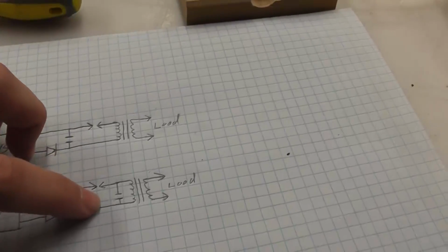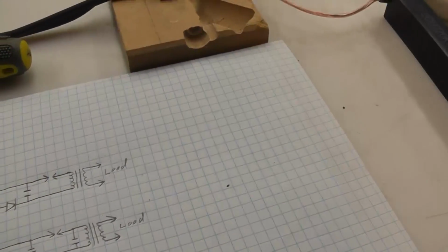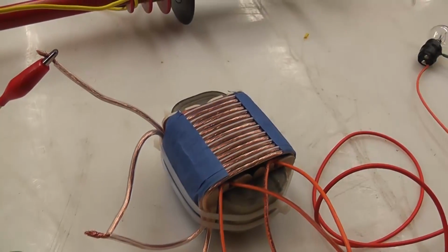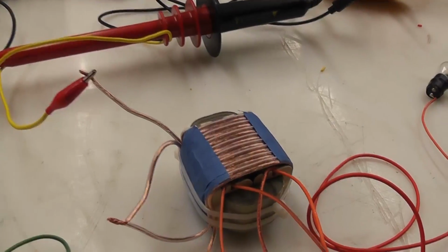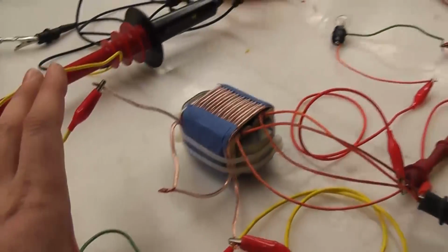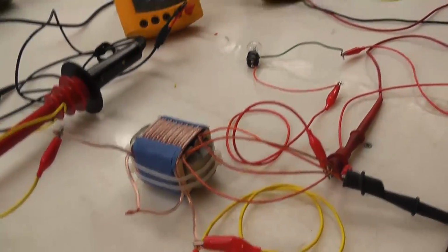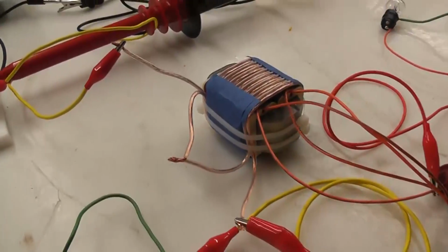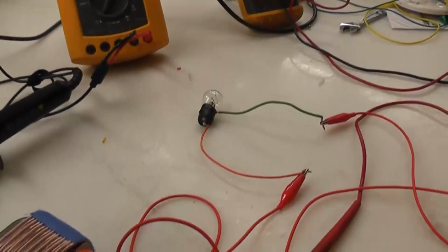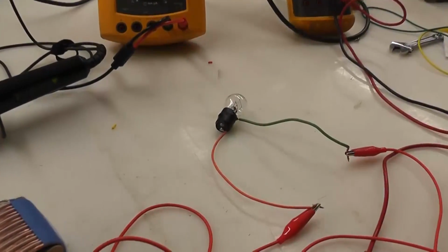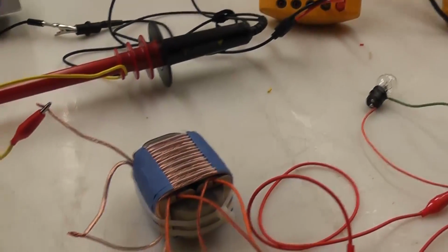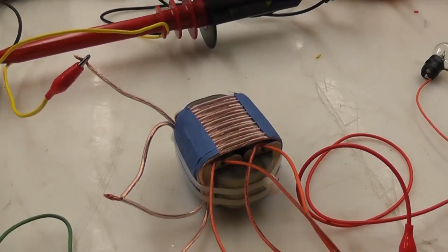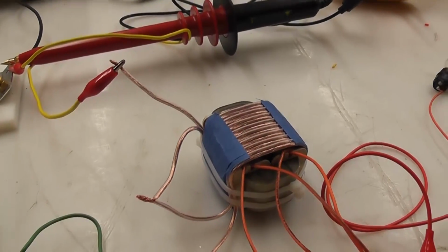And then whatever inductor you have here, you're going to have to measure it with your inductance meter, your LCR meter, and then find the right capacitor for you that's going to go across here. Will that work? I don't know. I have no idea if that's going to work. I have dropped a capacitor across that just to see what happens. A random one, mind you, and the light bulb gets dimmer, a lot dimmer. So I don't have even close to that capacitance. So can't do it.